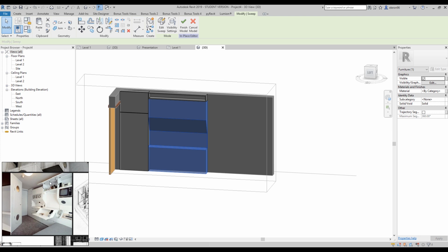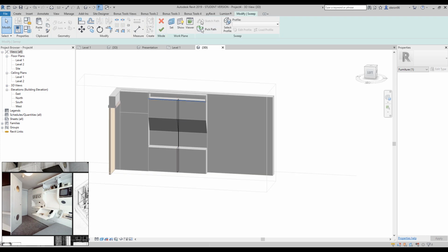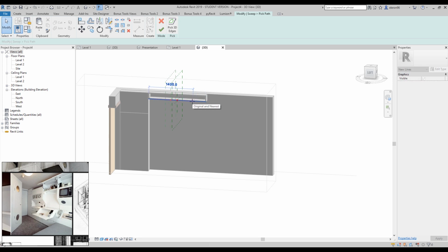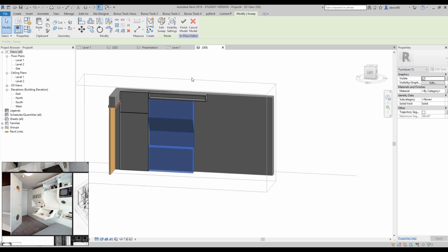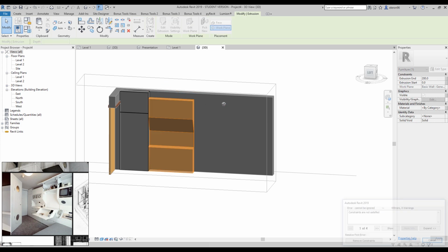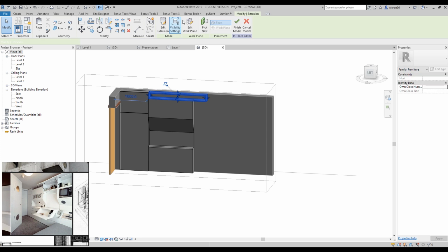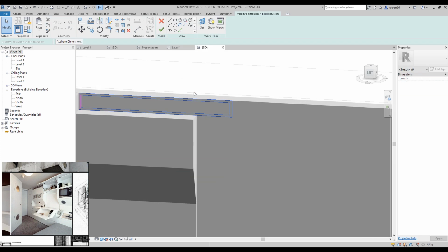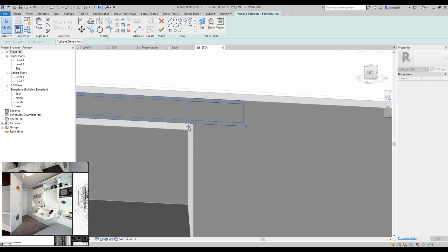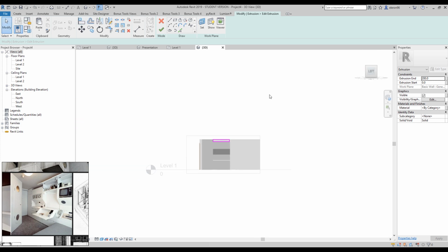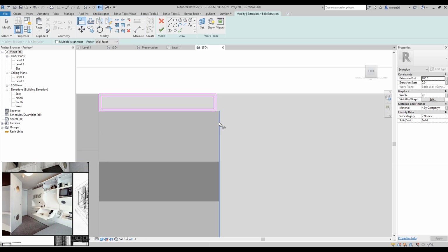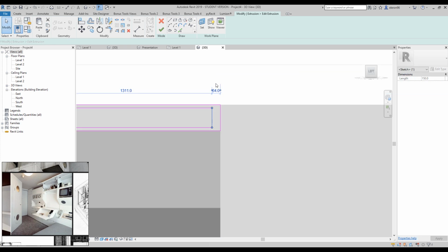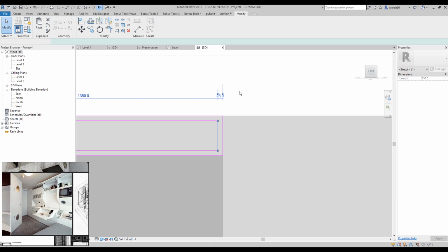but I cannot see any ducts here, but I don't think we have any there, right? So let's go to the sweep, and I will change the path. I will make it a bit smaller. Okay, and let's make it smaller too. We cannot do it like this. We should go inside the model, and let's align it. I will use the align command. Let's go to the left view, because we cannot use it without the left view. Okay, and here we know it's 25. Okay, nice. Let's say okay.